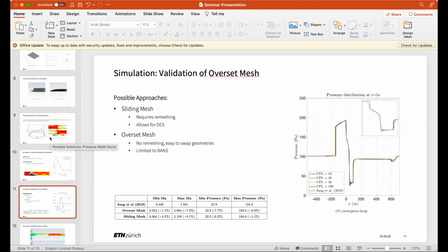And then second last question, what does the temperature in front and after the vehicle do? Do thermodynamic effects, for instance compression, have impacts on the flow? Yes, there's quite a large increase in temperature. I actually have that in front of me, so I'll be able to tell you exactly. So there's about a 200°C increase in the air temperature in front of the pod,